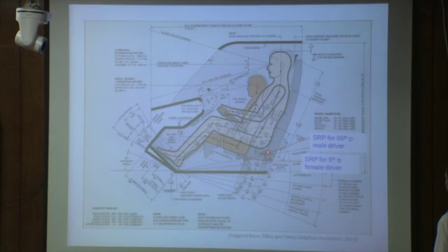On that seat, this point is SRP, because this is the midline of the compressed seat back and compressed seat pan. From side view, this is the position of SRP for the 95th percentile driver, because this seat has been adjusted as per the 95th percentile driver. So this is the SRP for the 95th percentile male driver.